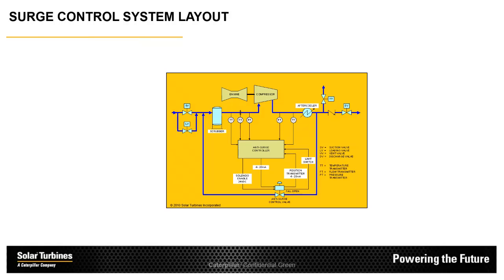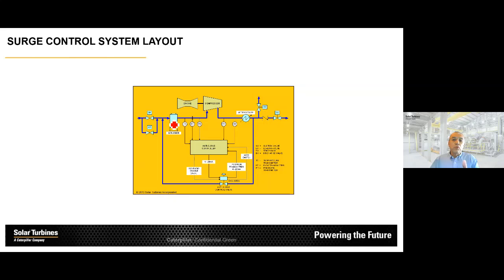There is in practically all modern centrifugal compressors a second system to control the flow or the operating point of the machine, and that is the surge control system. If the flow that's available to the compressor drops below the low flow limit of the machine, we can recirculate gas through the control valve back into the inlet. That's basically what recycling is. Therefore we are able to run our station, for example, all the way down to zero flow while still keeping the compressor online. So it's really a method of increasing the overall range of the compressor station.